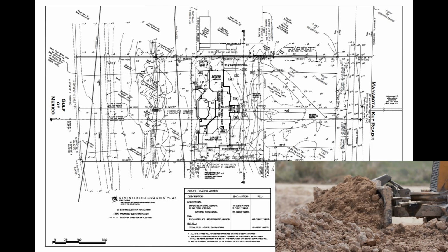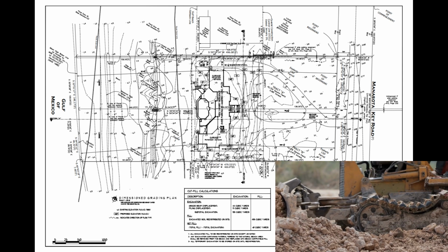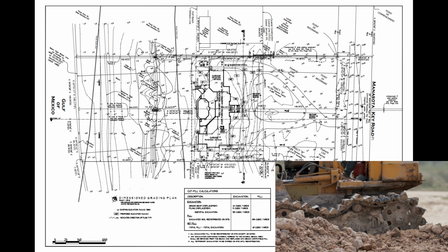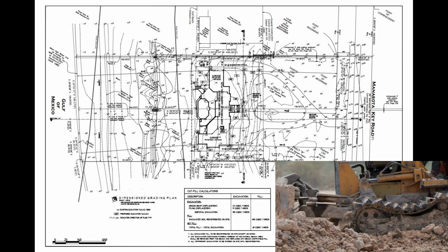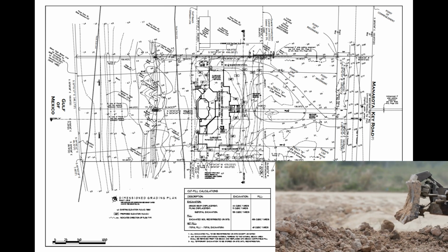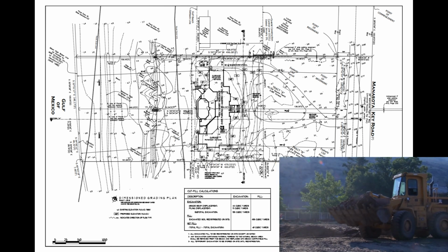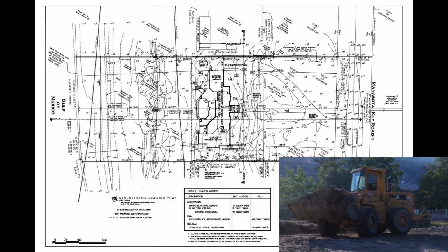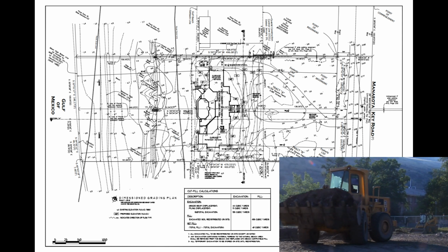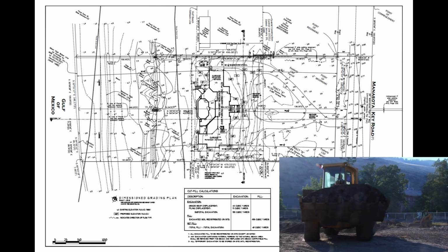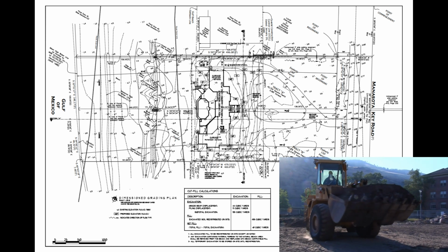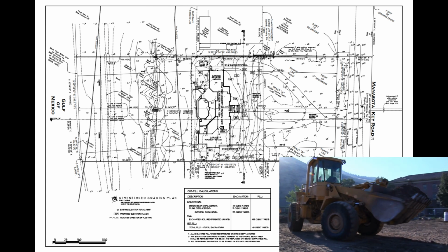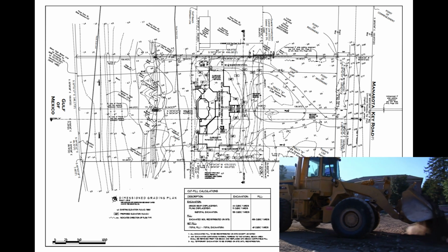The grading plan, site plan, and civil plan are usually interchangeable. They have the sheet designation of C sheet, GP sheet, or SP sheet. Grading plans usually show the building within the survey. They also give elevation markers telling the contractor how high with respect to sea level the land must be. The grading plan should also show the site drainage plan.